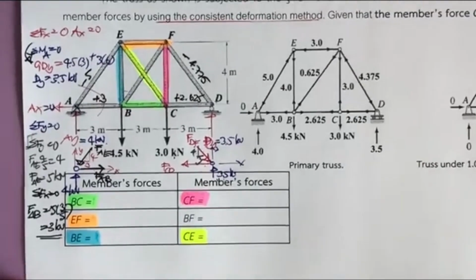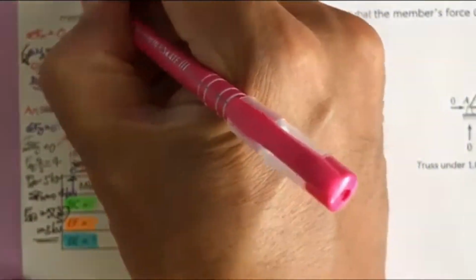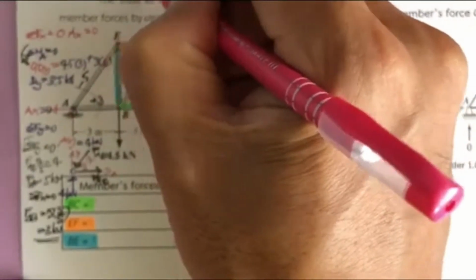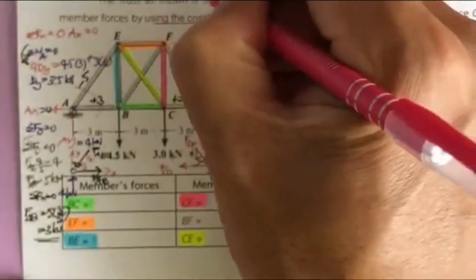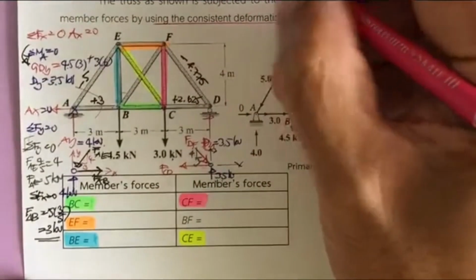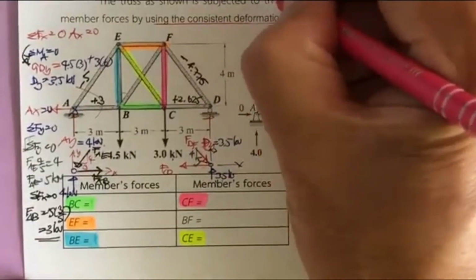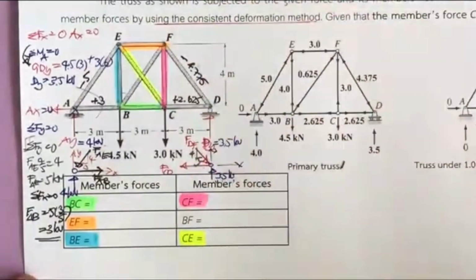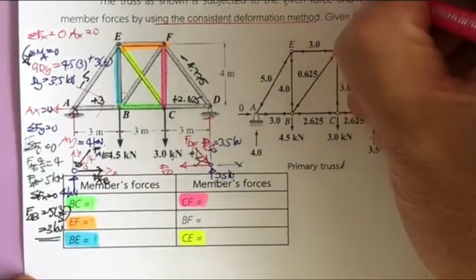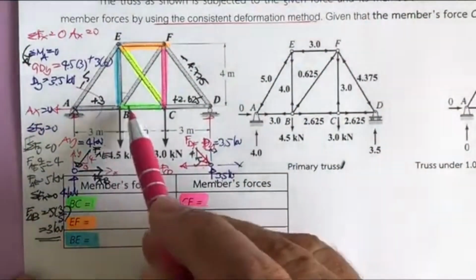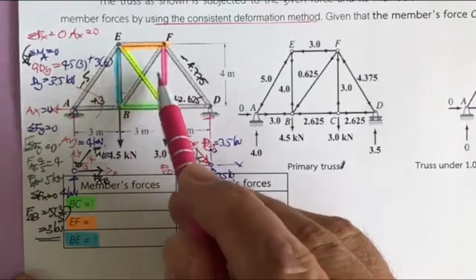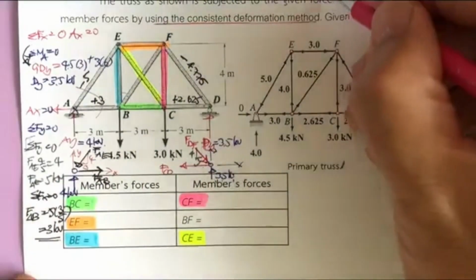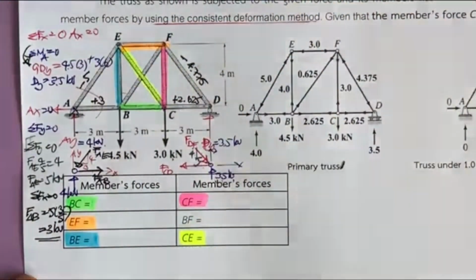And how do you check this structure? It is going to be a statically indeterminate truss, and it says internally. Internally is due to what I just explained to you. You check with what? B plus R. Okay, how many B? 1, 2, 3, 4, 5, 6, 7, 8, 9, 10. B is 10. Plus R, you have A sub x, A sub y, and this y, 3. So this is going to be 13.